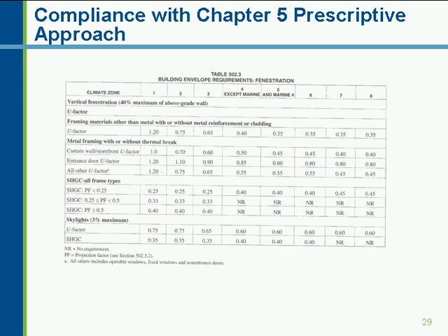Now we're going to start looking at fenestration and glazing for the building. And there were some changes made to the fenestration requirement table. I've highlighted some of them. We're going to go ahead and walk through this so we can learn how to use this particular table if you're not familiar with it. Again, you're only allowed 40% maximum window wall ratio for a building. If you have greater than 40%, you either use a performance-based approach, Section 506, or you go to ASHRAE 90.1 2007 and comply with the entire ASHRAE standard.